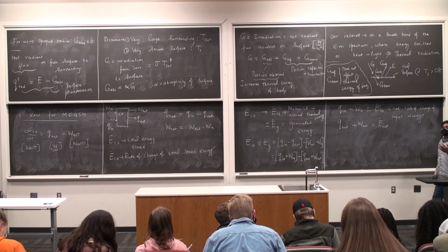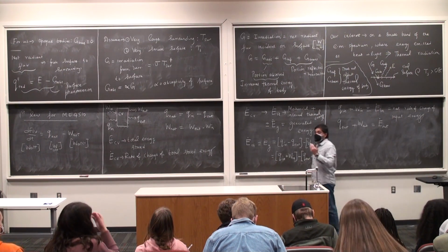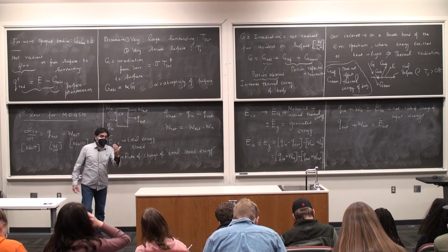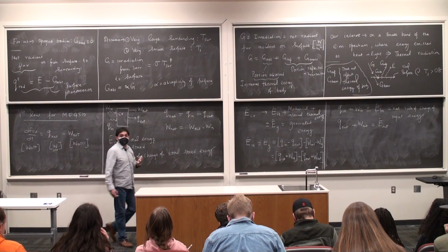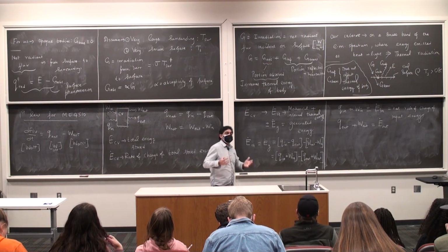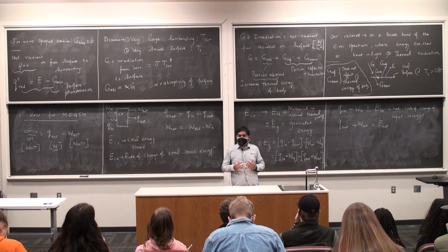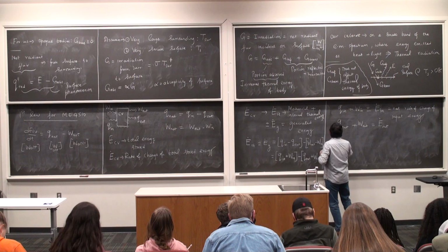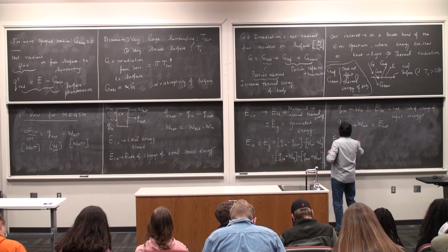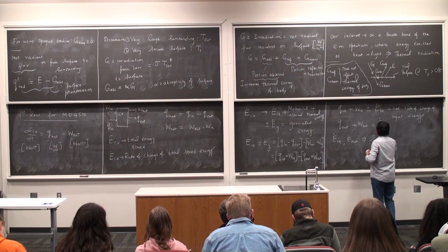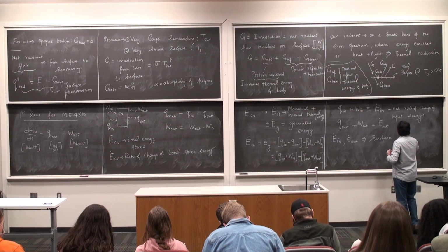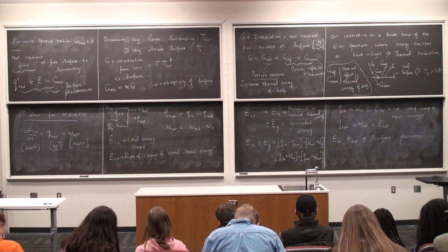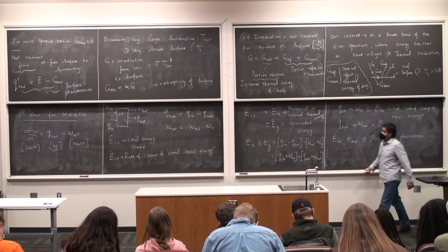E dot in and E dot out are surface phenomena, which means they are taking place at the control surface. E dot stored and E dot generated are volumetric phenomena, which means that they are taking place as a function of the volume of the control volume. Okay, so these are surface phenomena. E dot generated and E dot stored are volumetric phenomena.